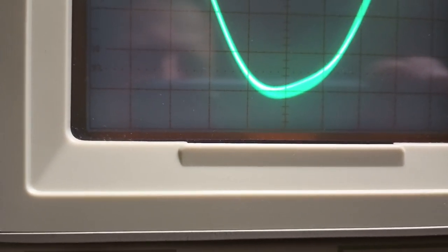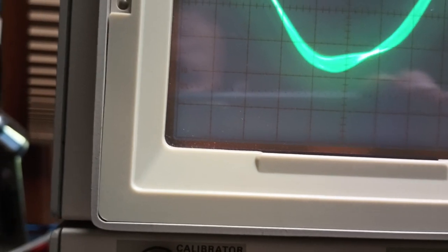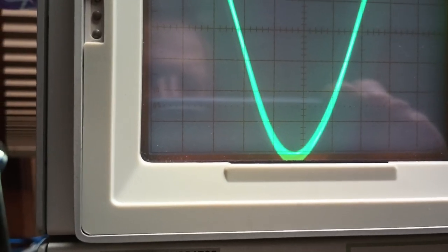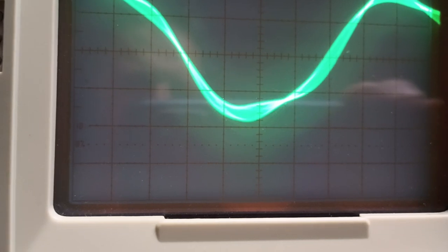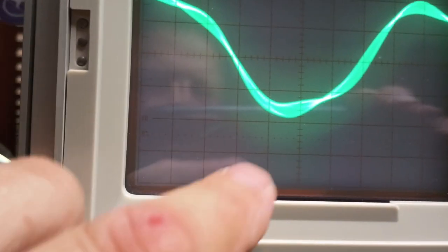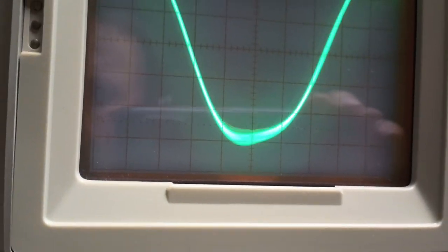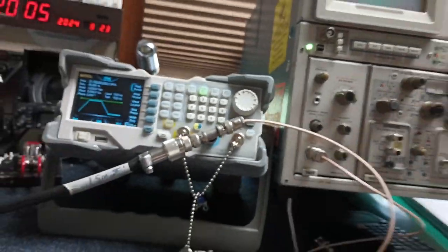So a match is kind of indicated by all those wave shapes lining up. When the tuning is really turned off, 23 megahertz, you see these waves cycling through here, left to right, and doing all kinds of weird stuff. See, there's a big change right there. There's a wave there and a wave there and a wave everywhere. So this is kind of a crude TDR test. It's the best I can do with this cheap Chinese generator, apparently.